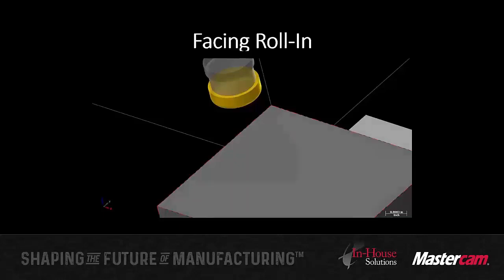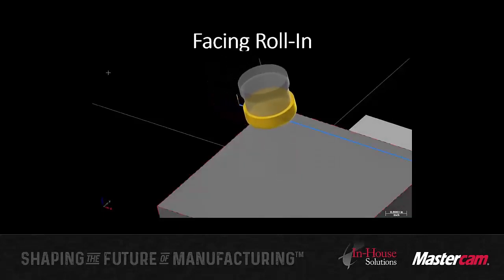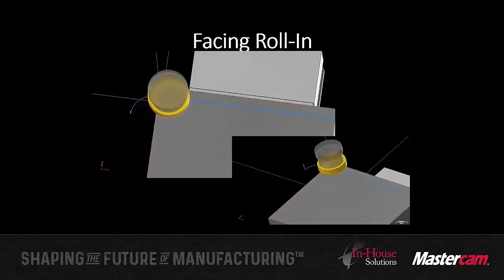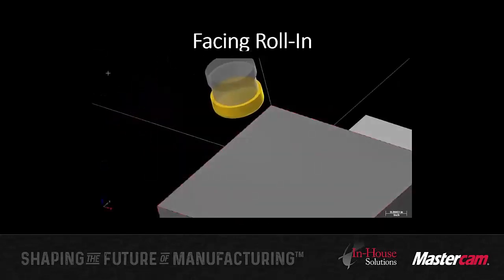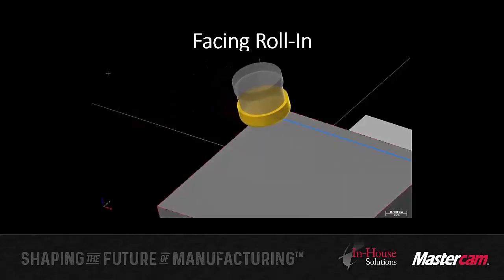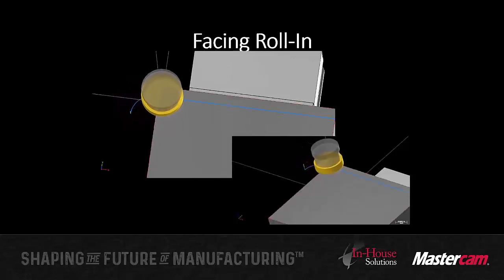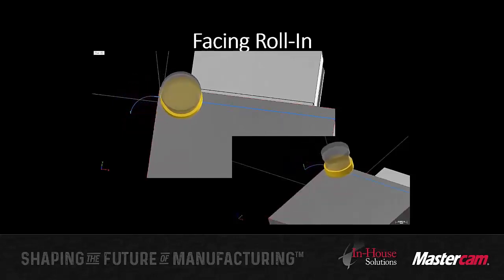So if I just play my video here, right away, you're going to see I'm just hitting full engagement onto my cutter. It's great, it's going to do it. But if I enable my roll in, what I'm actually getting is gradual engagement onto my part. As you can see, my tool fully engaging versus gradual engagement coming in from the side of my cutter into the full. So it's just a little easier for your cutters.